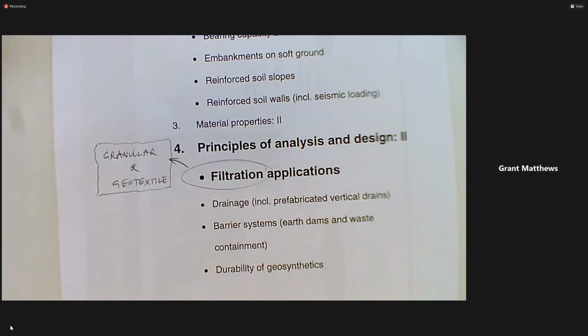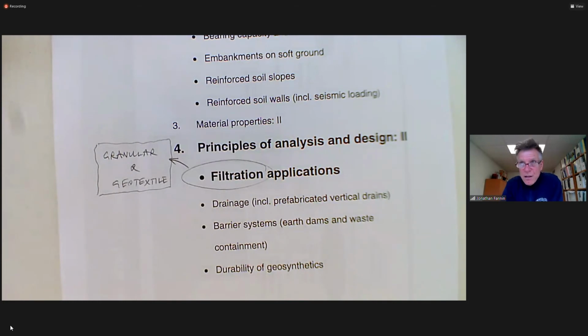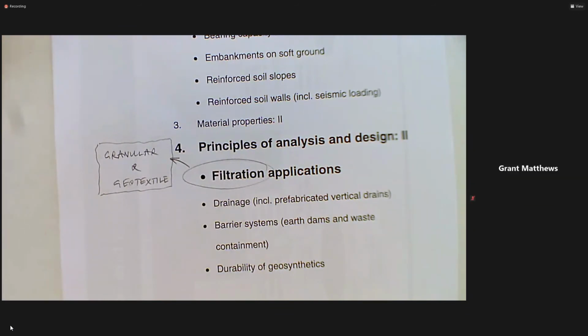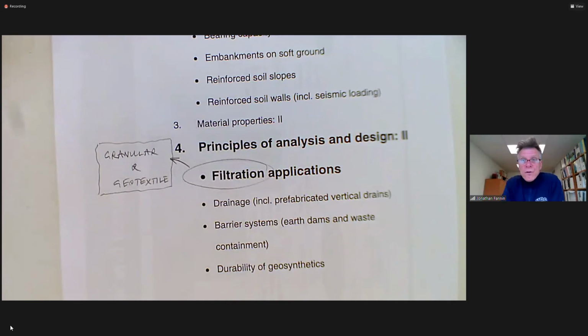Yeah. I got involved evaluating geotextile filters as covers for wick drains, but actually on a tailings deposit to try and accelerate the drainage. And again, I'll draw a little bit upon that. The concern from the review team was that the geotextile might clog in attempting to dewater the mine waste tailings. And so we ended up putting quite a bit of effort into that and doing some testing actually here in the lab at UBC. But so interesting to learn of your wick drain experience, Grant. Jason?